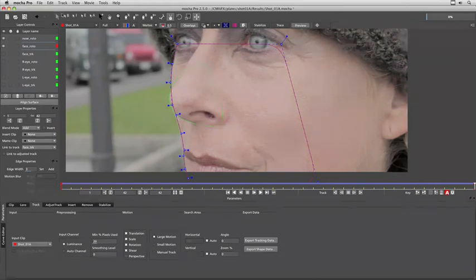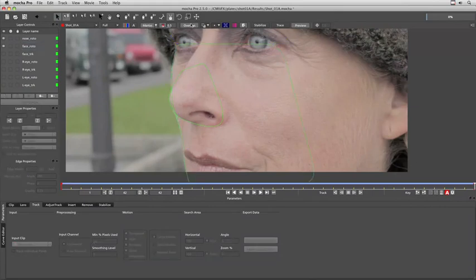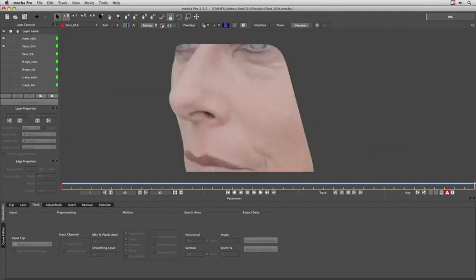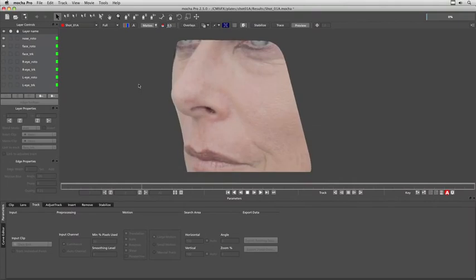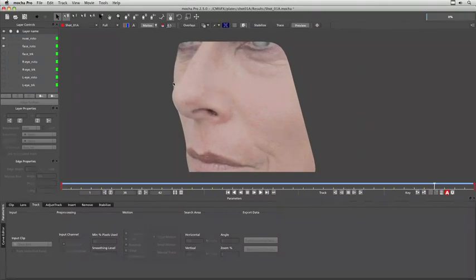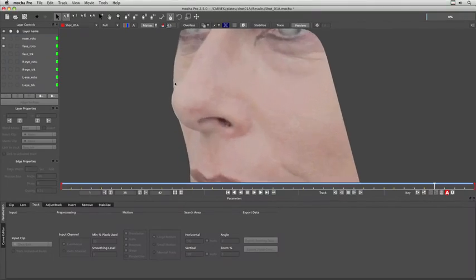I will turn on the matte, turn off the overlays, and now, because I have 2 layers, I need to change the matte behavior to all mattes to be able to review both layers at the same time. I will click on the bucket to review over a neutral background, and let's take a look on the results of the rotoscope. It's looking good. There's only a little bit of background contamination here on the end of the sequence.